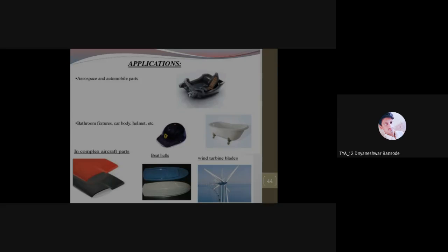See, the dimensioning or shaping of the part is required with proper exactness. Whatever design is provided, we need parts with very little tolerance, very little allowance. So exactness is required in case of wind turbines also, because wind turbines are designed very carefully. Getting it? Maybe the shape will be simple or intricate, but that can be possible with injection, sorry, transfer molding rather than compression molding. So intricate shapes are mostly done with transfer molding.